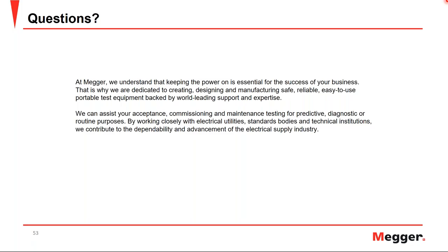And if the tan delta values are already bad, do we need to do a DFR? Well, that depends on what is being considered bad. If they are just a little bit above the limit established by the standard, such as 0.5%, then that is where power factor has its limitation: you don't know if it's really bad, or if you have a very small increase, or the values are starting to change but only very slightly.